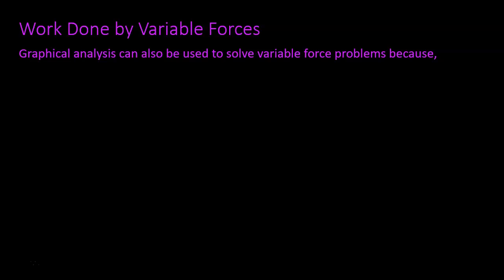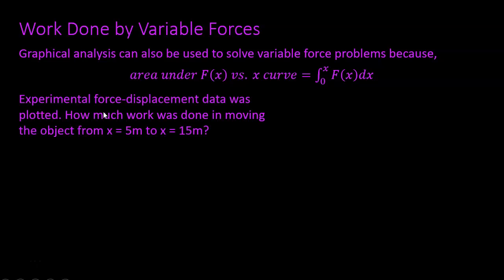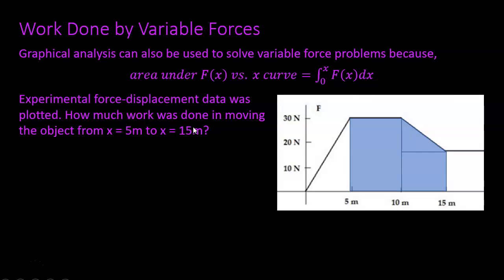Let's move on and look at another way of calculating work done by variable forces. We can use graphical methods to solve variable force problems because the integral used to calculate the amount of work done is equal to the area under the curve. For example, suppose we had experimental force displacement data. We plotted it and we wanted to find out how much work was done in moving the object from 5